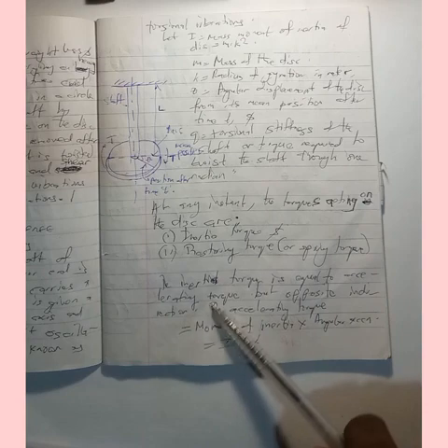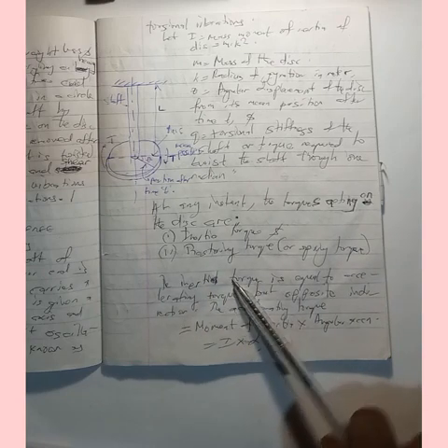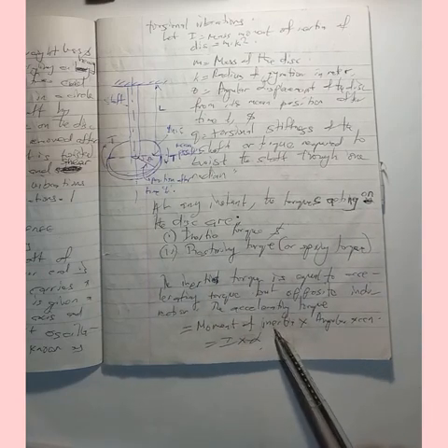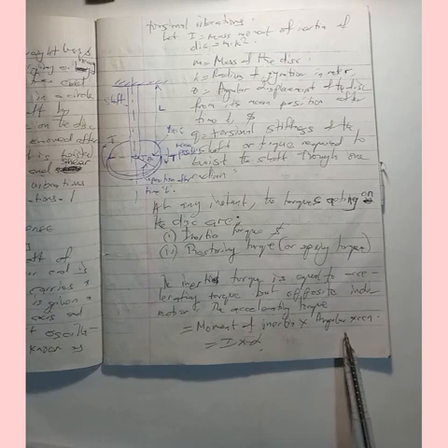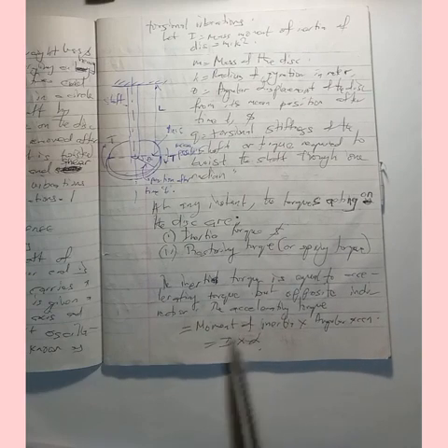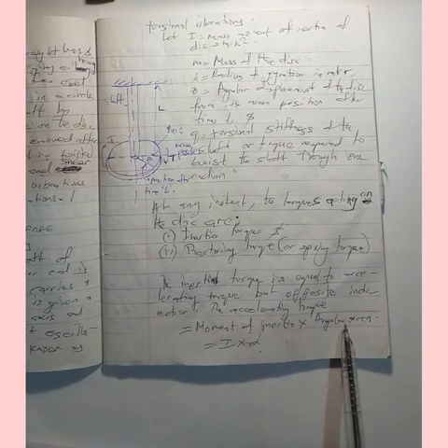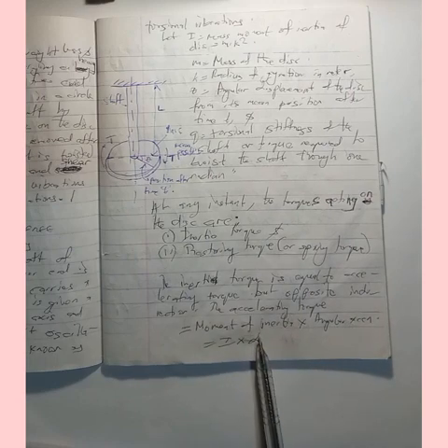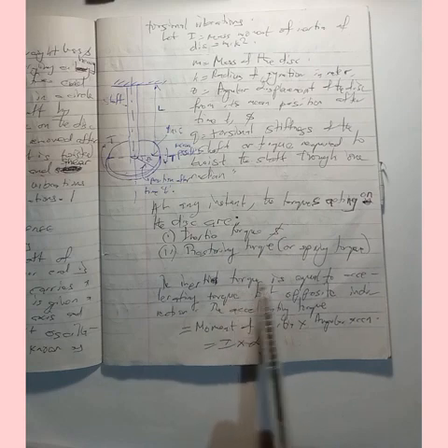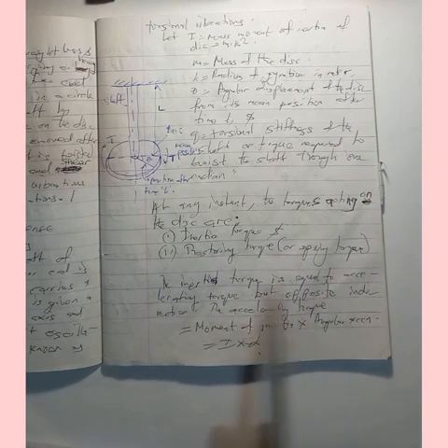What's the formula for inertia torque? It is given by moment of inertia multiplied by angular acceleration. The moment of inertia is I, the angular acceleration is given by alpha. But take note that we've been told that the inertia torque is equal to the accelerating torque, but opposite in direction.